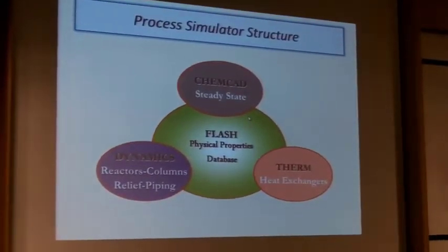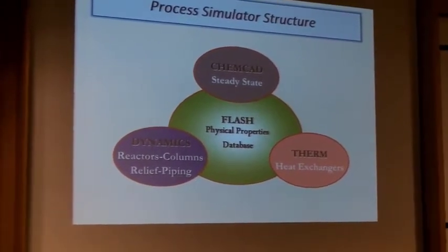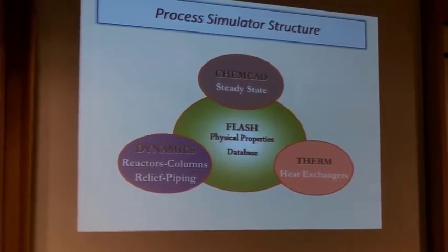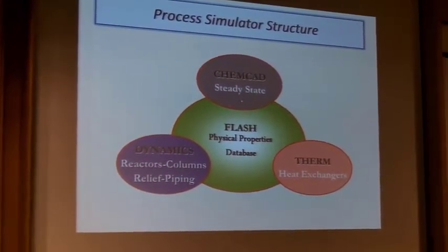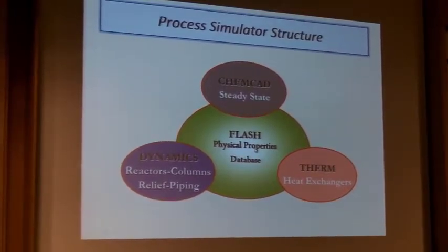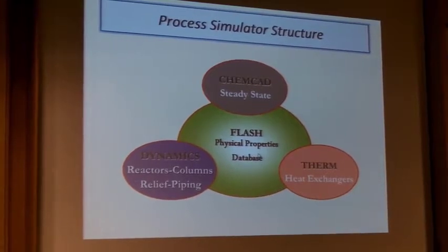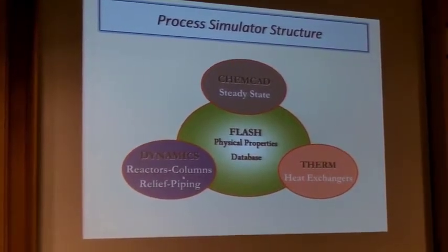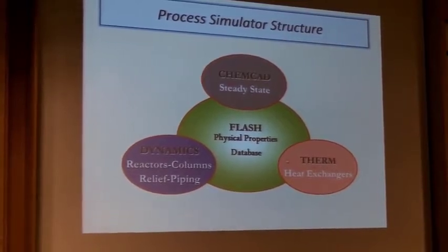The simulator I work with is ChemCAD, but there are several other simulators. There's HYSYS, there's Aspen, there's various other people. The structure is you have a steady state module which sits on top of physical properties and the basic structure of the software, which is applicable to all modules. You've got the dynamics, which is what we're going to talk about, and you've got heat exchangers. So that's the basic simulator structure.